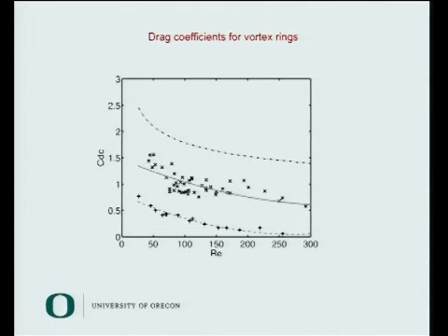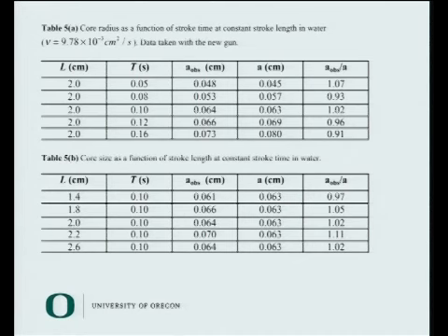So then the other thing is that if this really is Reynolds scaling, then you should be able to do this experiment changing the viscosity. And I made some glycerol water solutions, which have considerably higher viscosity, 2 or 3 times that of water, and verified that the drag coefficient was a function only of Reynolds number and not of viscosity. So I think that story is pretty well understood.